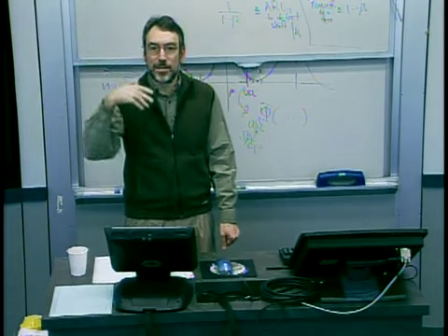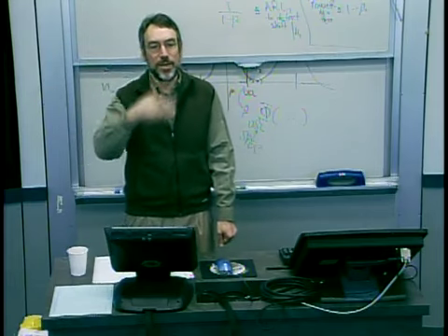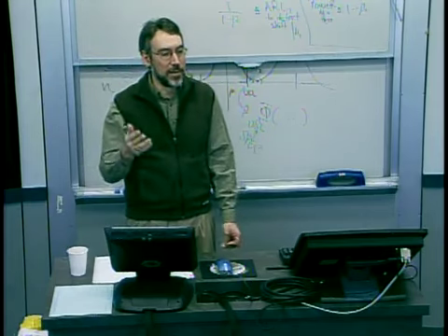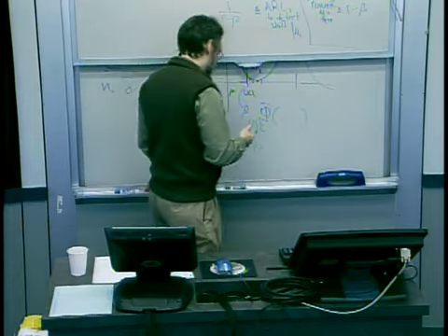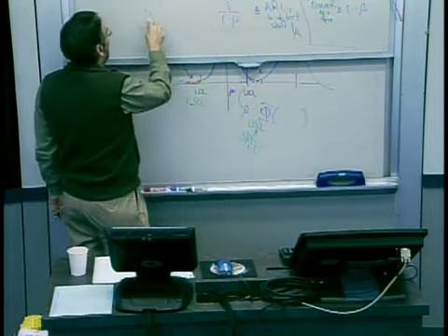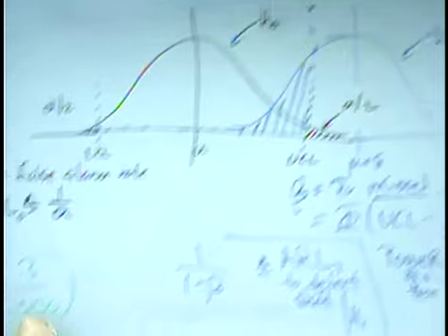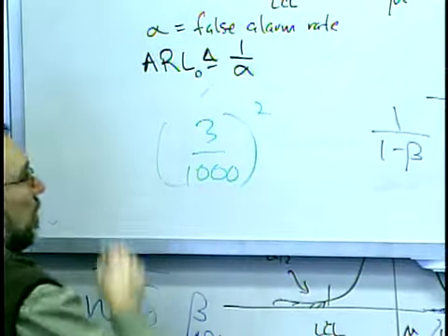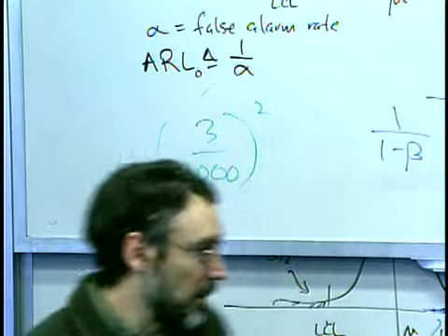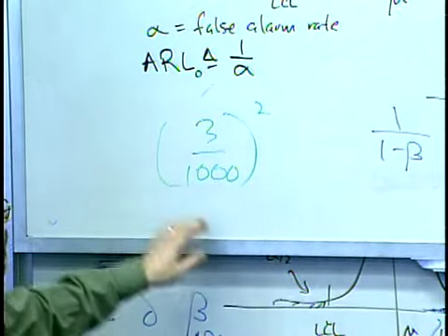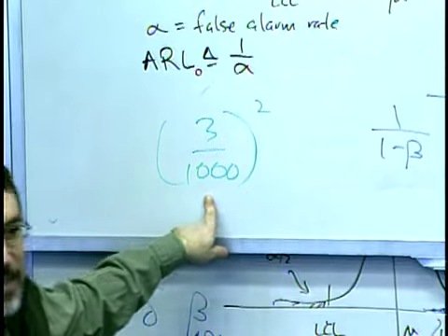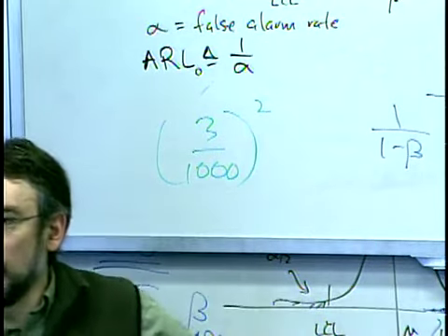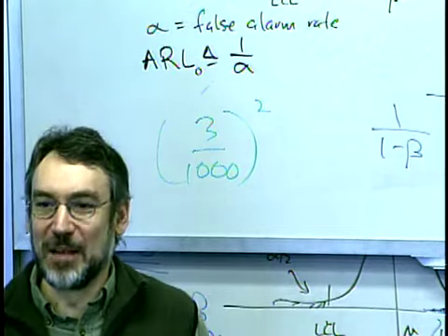as much stronger evidence. So in this case, roughly it's twice as infrequent, or not twice, but the product, right? The probability of seeing both of those points outside of the control limit, and again, not alarming on the first one, is the square of that. So that's a very infrequent thing. Then they say, I think there's really something wrong.